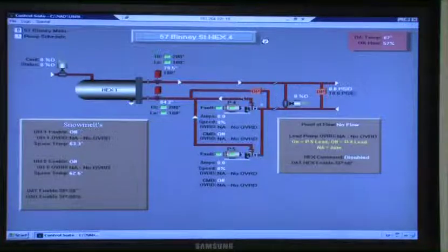And this differential has got to be up at the heat exchanger. The pumps are up there? Pumps, for the flow switch, to say status. Proof of flow. So then we have the proof of flow, that you see no flow, that's the switch for them. That's on the fourth floor. Low pressure steam coming in. So that's your low pressure steam coming in. That goes to the heat exchanger. Trap comes out, comes across.